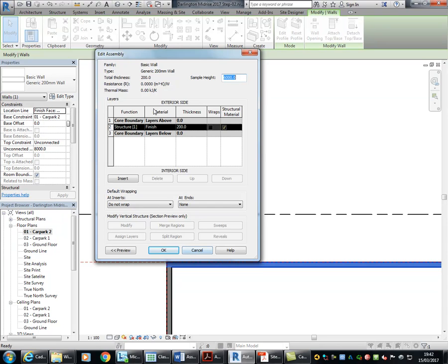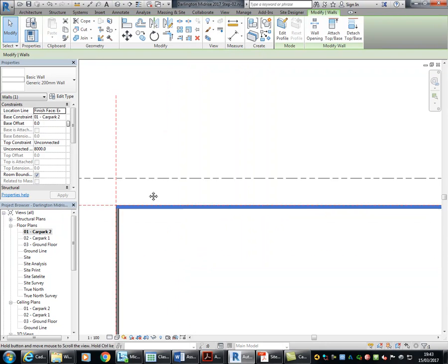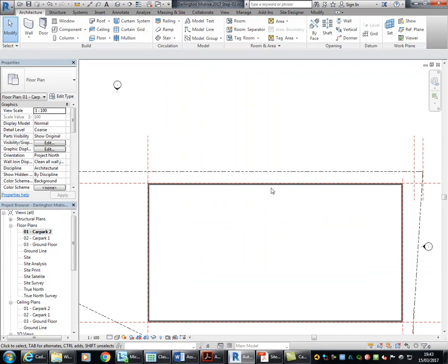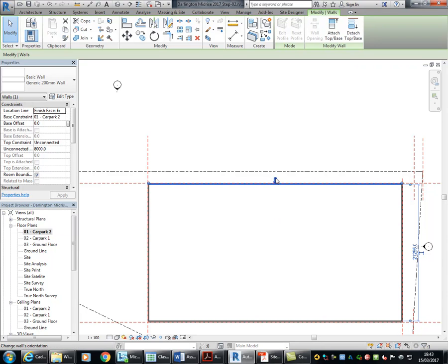So it needs to know that for the walls, but also when you join things like floors and roofs to your walls, it needs to know that. Don't be too worried about it. If you get it wrong, you can easily fix it. And you can tell whenever you select a wall just by looking at it in plan, these arrows. And this is pretty common with a lot of things in Revit. Those arrows should be on the outside.